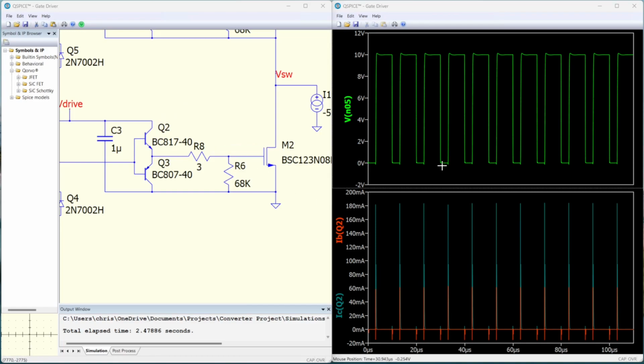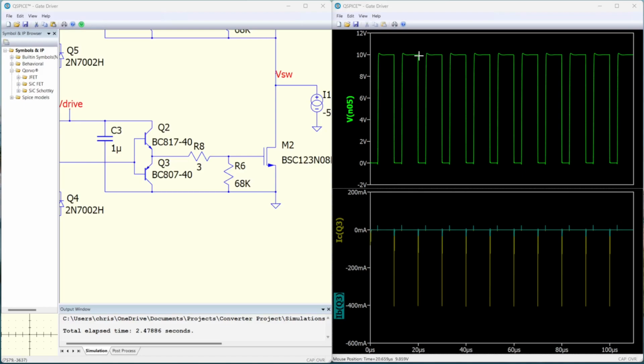The simulation is shown here. We have a positive voltage and the base current, and a higher collector current rushes into the gate source of our MOSFET. Likewise, when a low voltage is applied on the base of the PNP BJT, a higher collector current can flow, turning off our power MOSFET. A gate resistor limits the current that flows into the gate and is needed to limit noise and ringing.